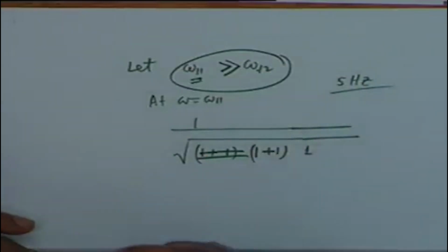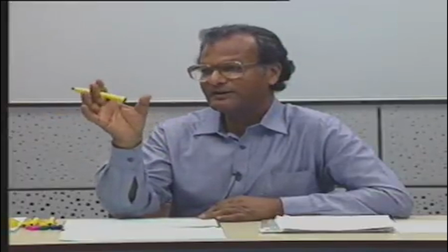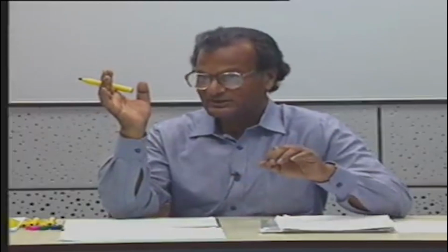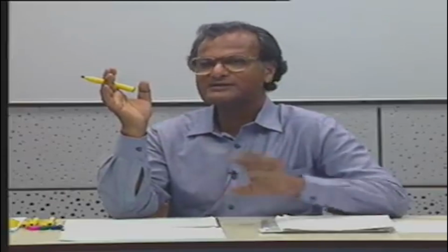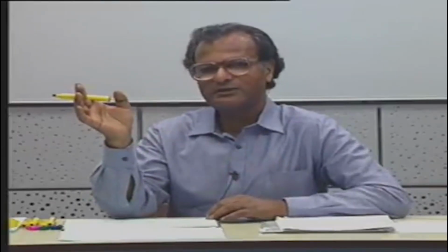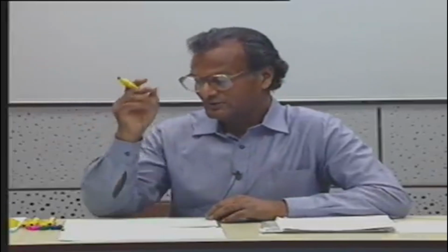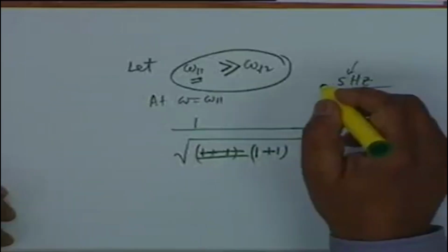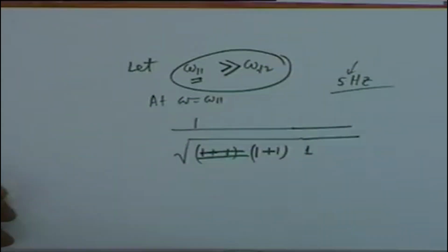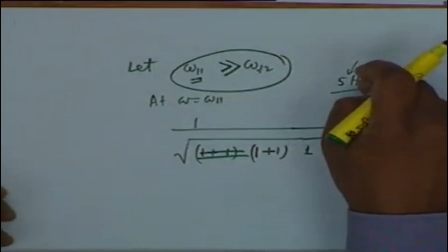You are told that audio frequencies go from 16 Hertz to 16 kilohertz, but if your amplifier satisfies only this, the drums, the left-handed baya in particular, which is very rich in low frequency, that sound is lost. All right. If you want a very high fidelity stereo amplifier, then you must go down to about 5 Hertz as the low frequency cutoff.